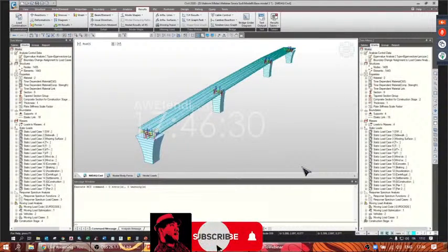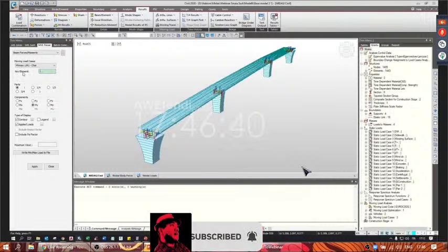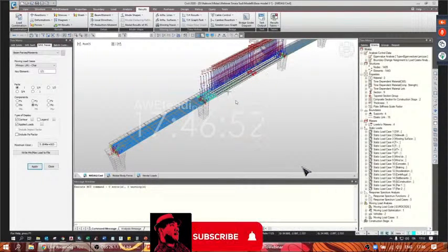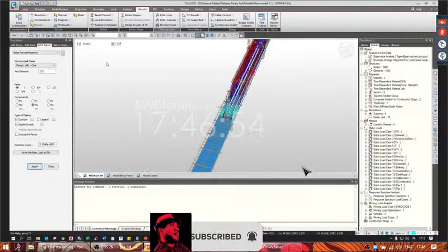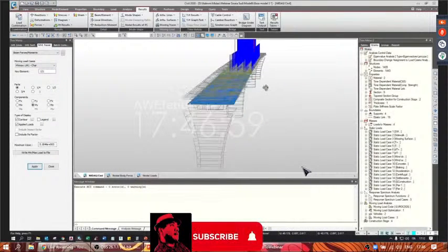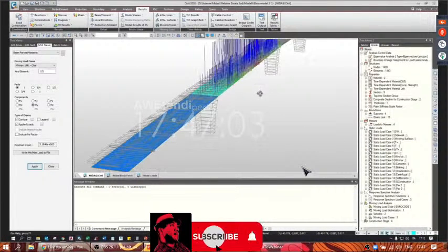Well, now we can see the traffic load effect in the moving tracer. Reinforces moment. Okay, we choose an element for the central span, for example, the 121. And here we can see the load distribution that maximizes the Load Model 1 characteristic. We see that in this case we don't have line loads, but they are surface loads.